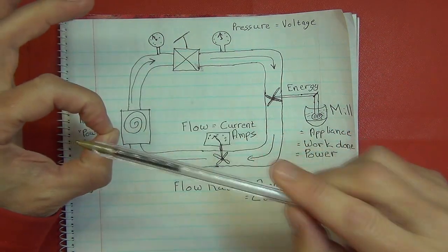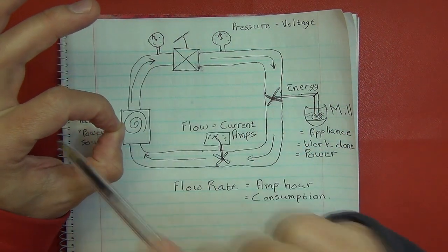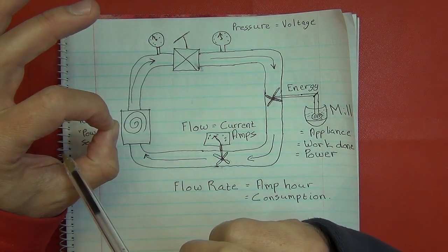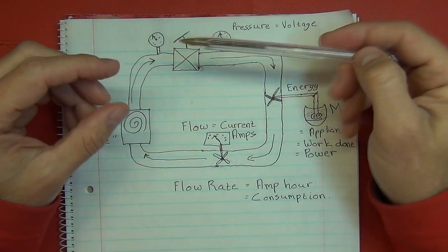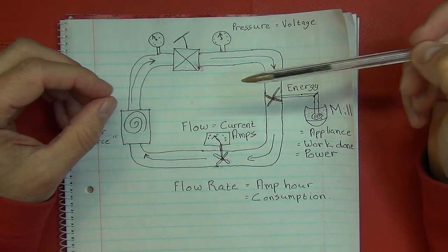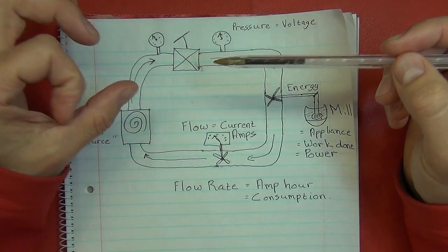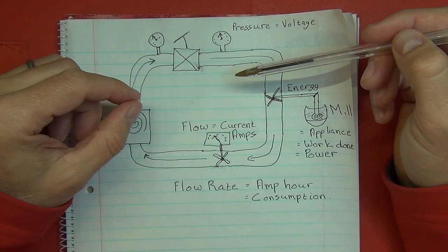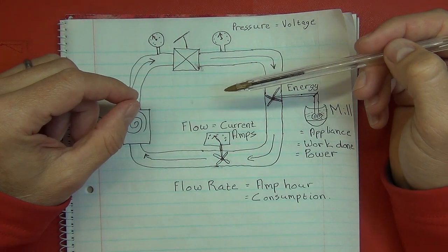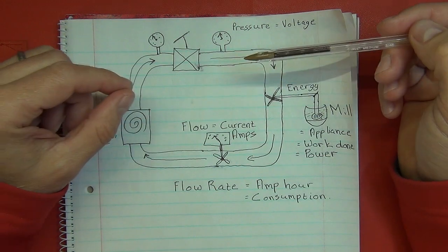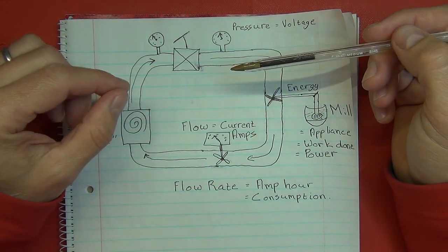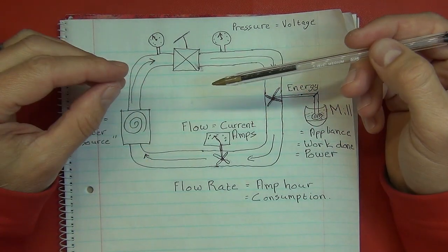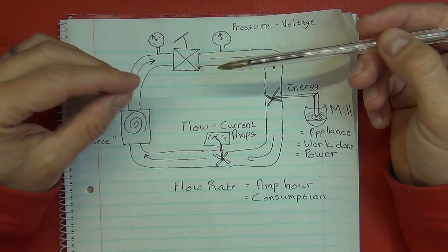You need far thicker wire to make it easy for the electricity to go through for direct current than you do for alternating current. The other reason AC is used is that you can generate far higher voltages with alternating current, and it's far easier to transmit higher voltage over long distances and then transform that down to a lower voltage and get the current back once you get to a neighborhood or your house.